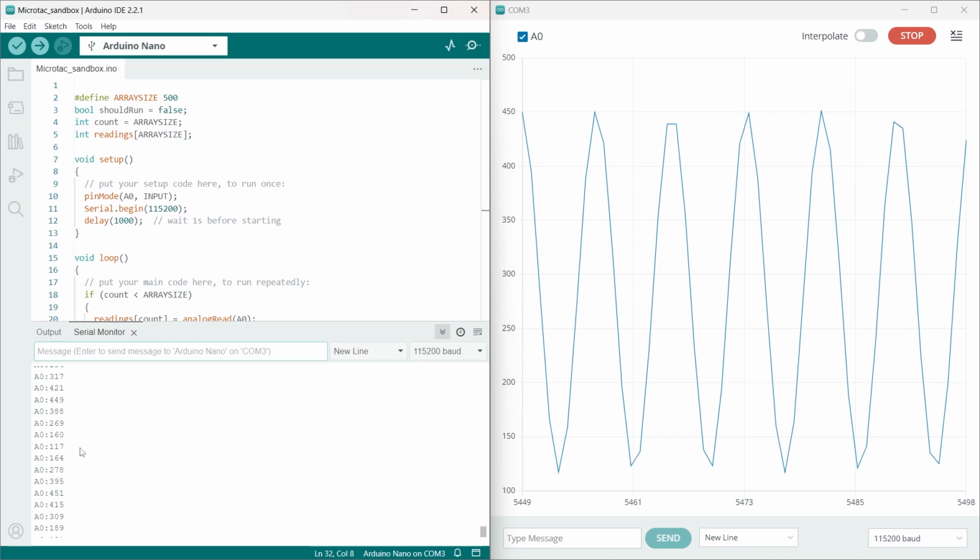And doing that, stepping through here, I've done that offline, and it looks like I'm getting about 10 samples per period on this 1 kilohertz wave. So 10 samples over 1 kilohertz is approximately a 10 kilohertz sample rate. That makes sense, that's what I would expect to see here if, in fact, the 328 is running as fast as it can without any other inefficient loss of clock cycles, which gives me about a 10 kilohertz sample rate for that A to D conversion.